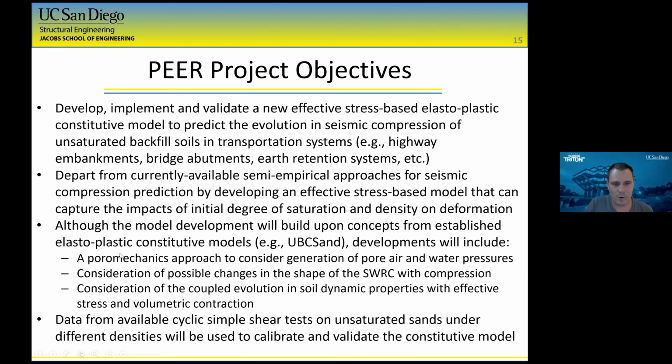We want to add a pore mechanics approach to better consider the generation of pore air and water pressures. We want to look at changes in the effective soil retention curve, and also look at how the soil dynamic properties are going to evolve as the effective stress changes. And then we're going to use some results from some simple shear tests to calibrate and validate the model.